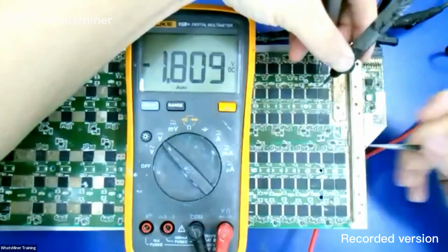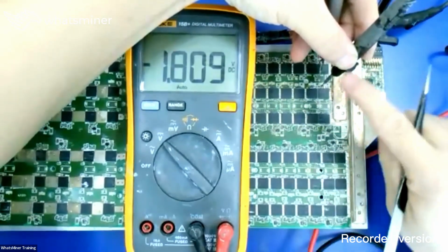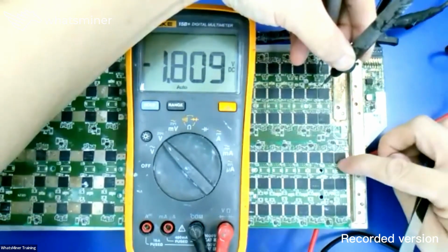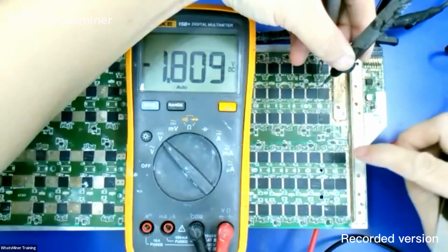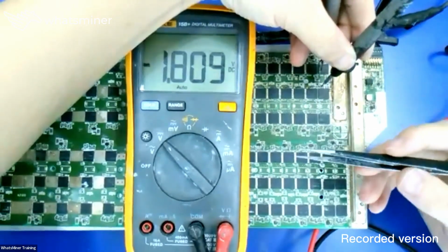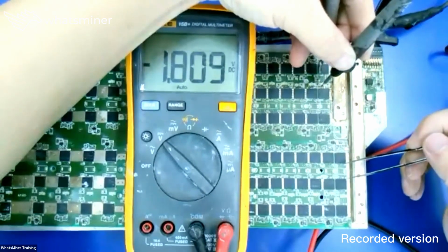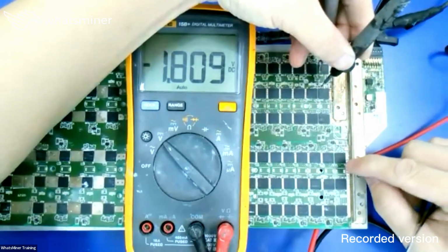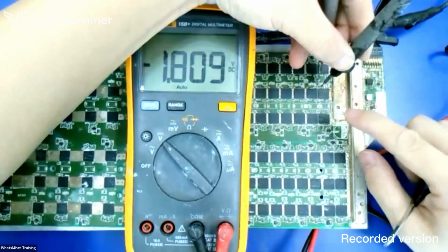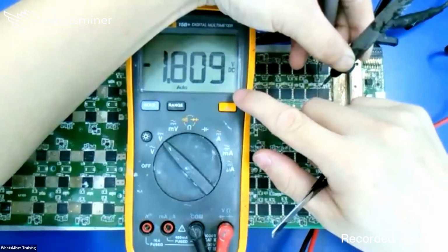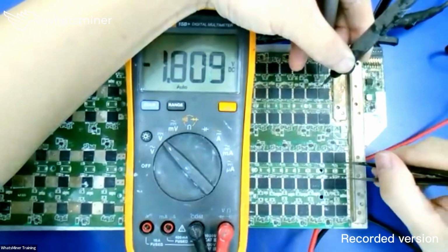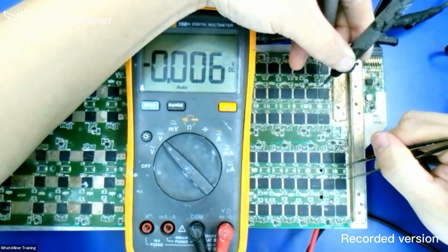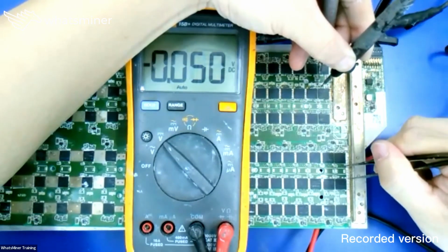And the RxD is transmitted from the first one to the last one. It sets the 1.8 volt from the first chip to the last one. Now I use the tweezers to short the RxD to ground at the first chip. It means I set 0 volt to the last chip, so it will fall to 0. I short the RxD to ground. Now you can see on a normal board, it can fall to 0.